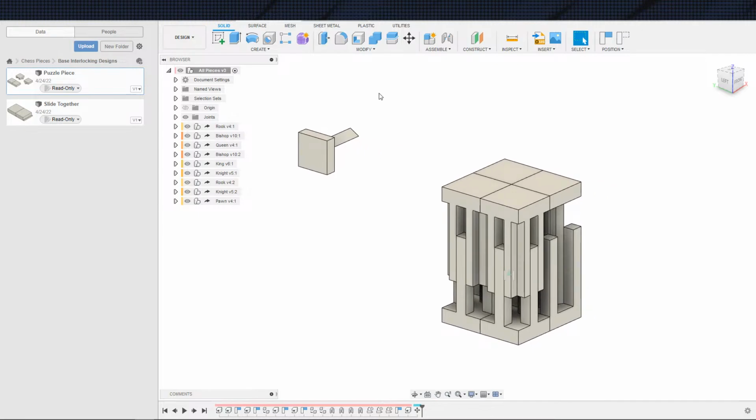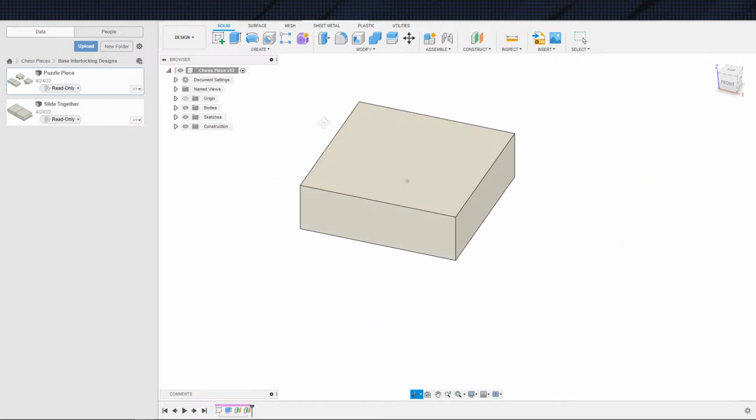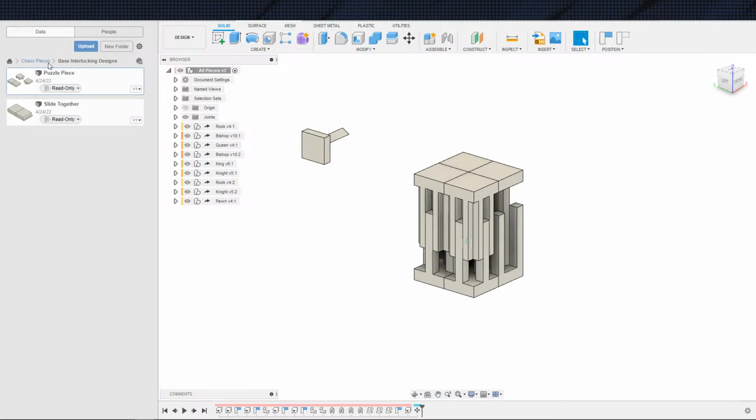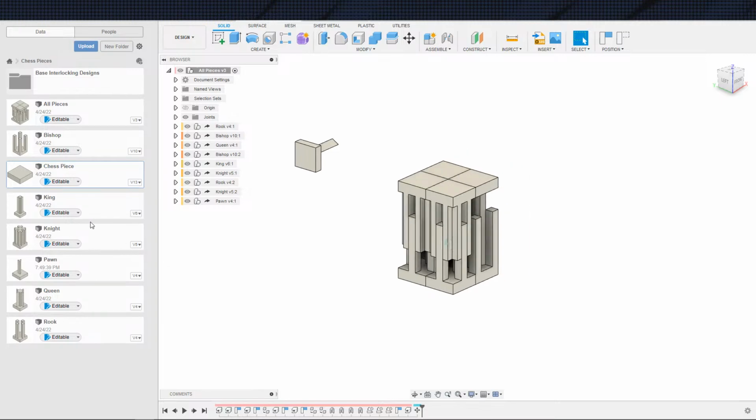So, things we got to do in order to achieve this, and again, we're trying to get this all done in one stream. This base is going to have to be modified without modifying the pawn base, which is a problem. So the most logical thing to do would be to take this, derive this base chess piece off into a pawn piece, and then into a connector piece, let's say. And then the connector piece gets imported into all the major pieces. Then the pawn base would be different from the major piece connectors, and we'd be good.